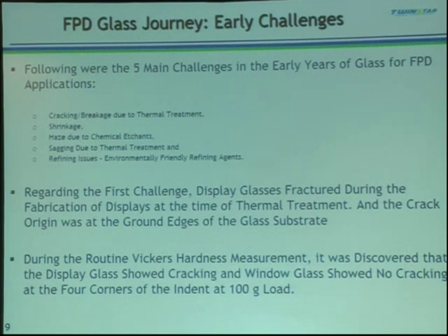But fracture toughness measurements used to take at least 10 days, because 7 days would be gone for sample preparation. The sample preparation would involve such intricate things that when the samples came back and you did the testing, there would be some artifacts of experiments, and you would not trust the data.